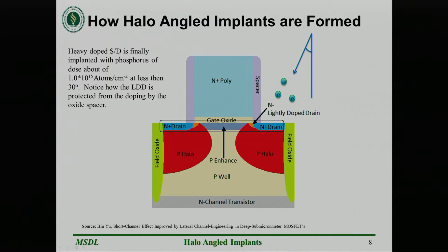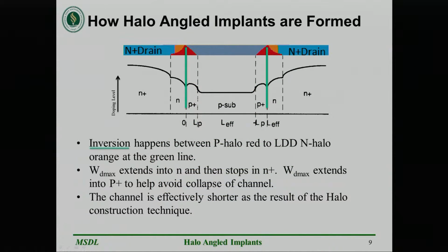Now I'm going to talk about the channel area inside the box. You can see below the boxed colored channel an XY plot of the doping levels versus channel length. The greater the y-axis, the heavier the doping concentration at any particular point along the length of the channel. Two of the doping transitions have no inversion of doping, only different doping amounts of the same type. The only change of inversion happens on the edges where the vertical green lines indicate.